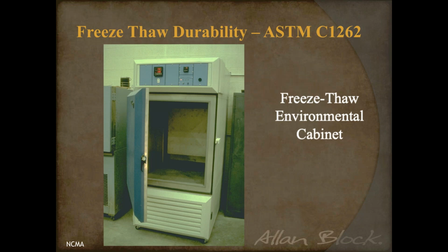The chamber that the testing labs use is very particular. It's a very expensive refrigerator. What it's doing is it takes our samples where it has water in the basin and it rises very consistently until the water melts, and then it turns around and brings the temperature down. So it's going to freeze and thaw over and over again every day, to the point where the test is complete.